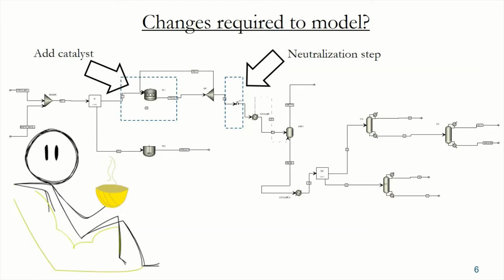Now, in the presence of these limitations, the alternative is to use the catalyst-free subcritical transesterification process, or utilize the hydroesterification process, right? The hydroesterification process essentially involves hydrolyzing the oil first, typically occurring at about 120 degrees. Now you hydrolyze it, you get your fatty acids, then you esterify. You can do this because the esterification step is always faster than the transesterification step when catalyzed with an acid catalyst, right? So you can split it into two steps, right?